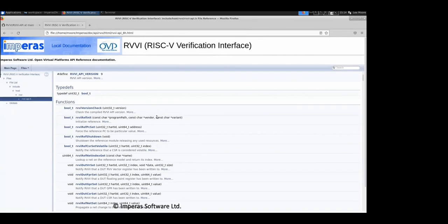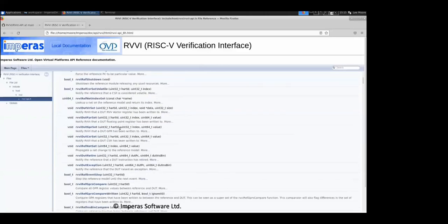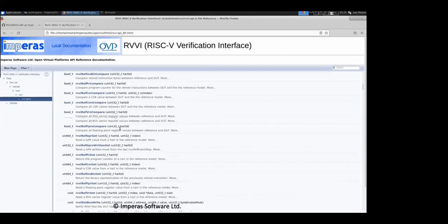But on top of that, you can then place extended parameters. So you can say, does it handle misaligned loads and stores? Which of the extension libraries are supported? So the model downstream that we use as part of the verification is highly configurable, not only from the standard set of specifications within the RISC-V organization's definition, but also for the custom extensions, be they CSRs or instructions. They can also be described as part of this environment and used as part of the entire verification flow. So as you can see, we've got a very rich set of primitives here that can be called directly.